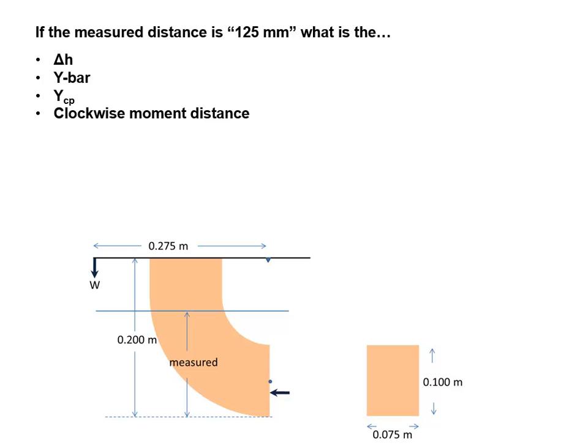And that's the theoretical hydrostatic force. Why is that theoretical? Because we've just used this equation, P bar times A. This is the hydrostatic force equation. We have another thing that we measured. Remember, by how many weights we put on to get it balanced? With adding those weights, we also have a measured hydrostatic force that we can come up with. But based on the theory of hydrostatics, those are the equations that tell us the location and the magnitude of the hydrostatic force.